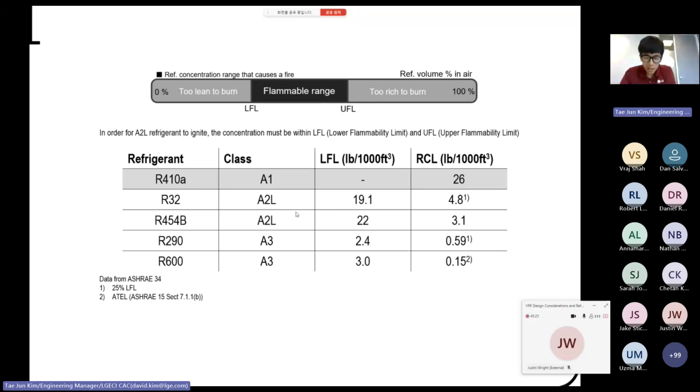I mean, you can kind of see how the gas catches on fire, but as soon as you release the ignition source, as soon as you remove the lighter, it does not ignite itself. It would be a different scenario if you used propane or butane. They would not be alive to take that video. So rest assured, R32 and R454B are very difficult to ignite.